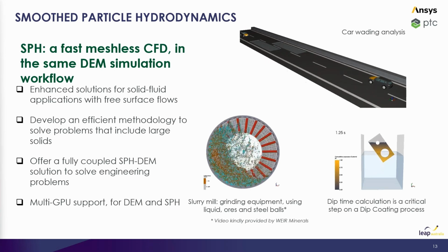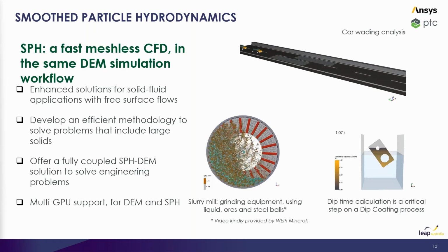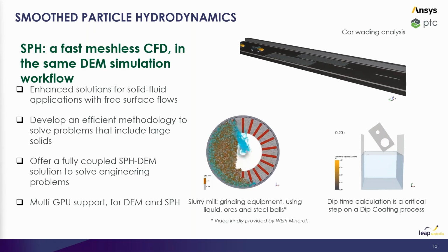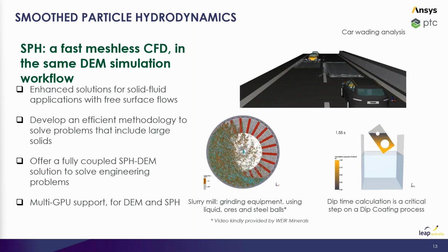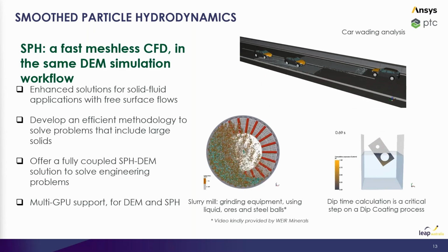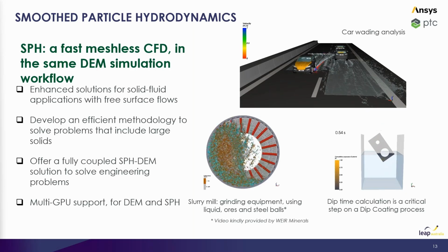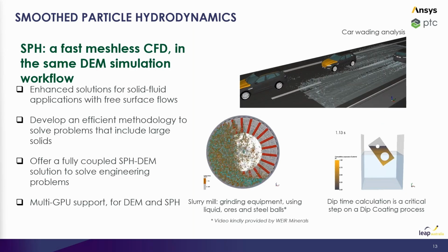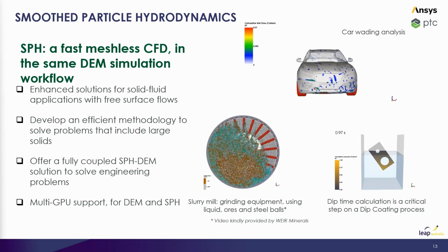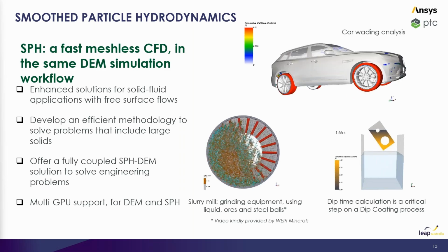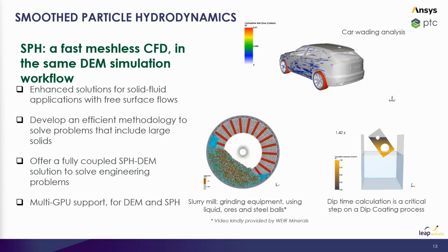Moving on to our second method of interest. Smooth particle hydrodynamics, or SPH, is a meshless Lagrangian computational approach. Now, this technique is much different to traditional CFD because it doesn't actually require a conventional mesh or a fixed grid, nor does it rely on empirical models to compute the liquid and solid phases or their interactions as before. So to put it simply, with SPH, the fluid is defined by a finite set of interpolation points.